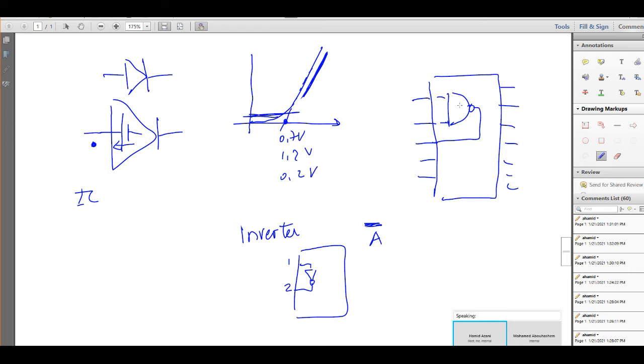If we have only a NAND gate, and we need to create this inverter or invert our input, still we can connect our input A to this input here. It will be inverted through this NAND gate, but we have to take care about this input here, because as I told you, TTL family will count 0 to 2.3 volts. It will be counted 0 logic, but suddenly if this one goes up to 3 volts and above, this will be seen as 1 logic.